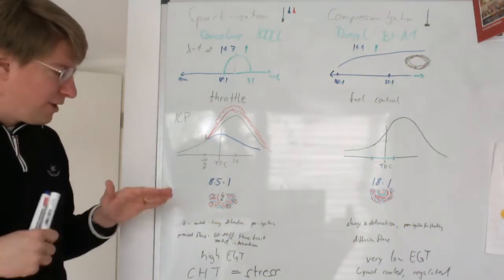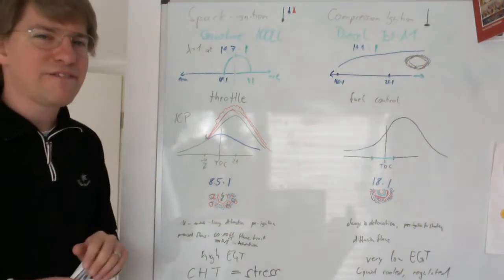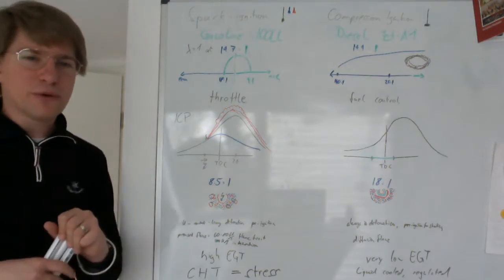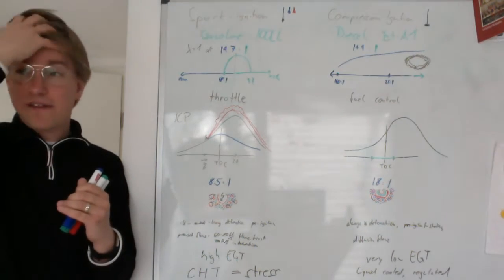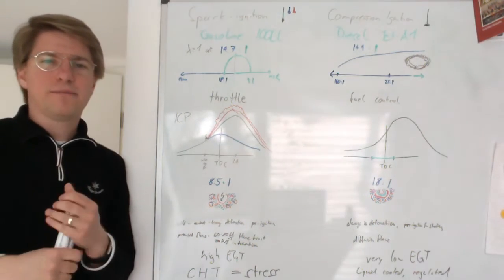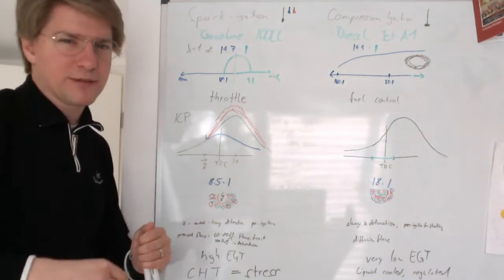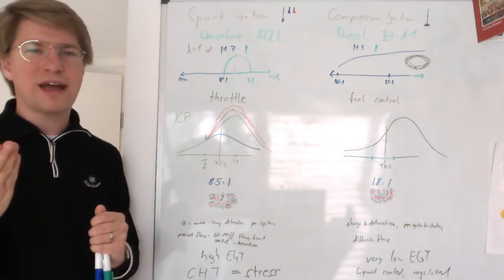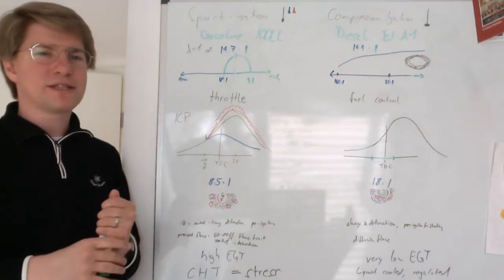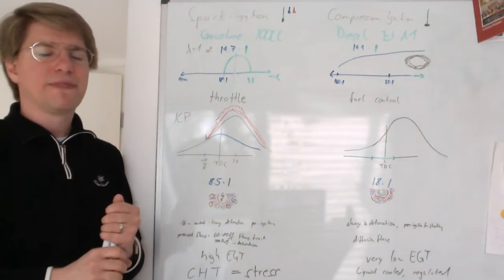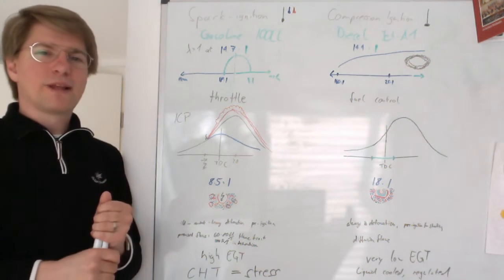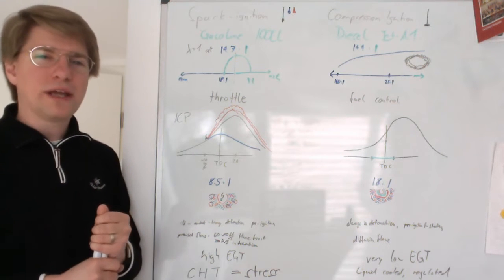Alright, so we've talked about mild, moderate, and heavy detonation. If you run the engine in heavy detonation, you can develop hot spots in the cylinder, typically part of the spark plug ceramic, or if you have some kind of deposit on the cylinder head in the first place, those can get glowing hot.